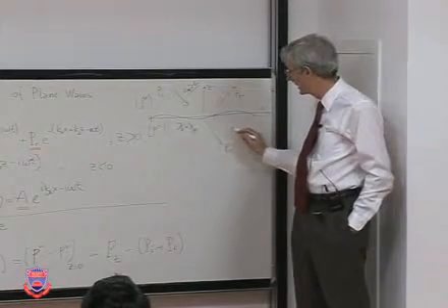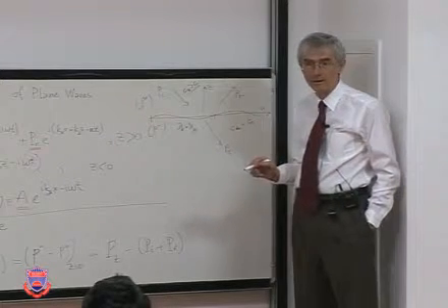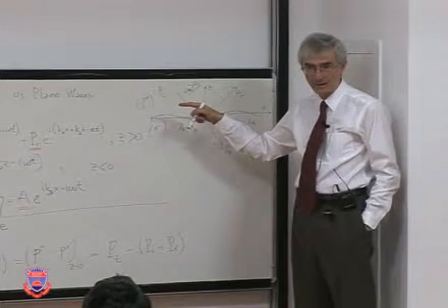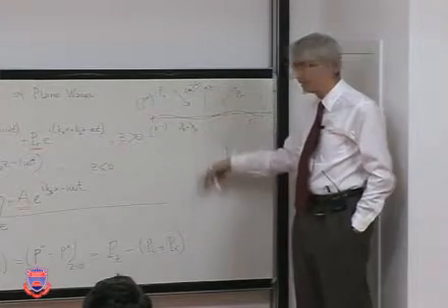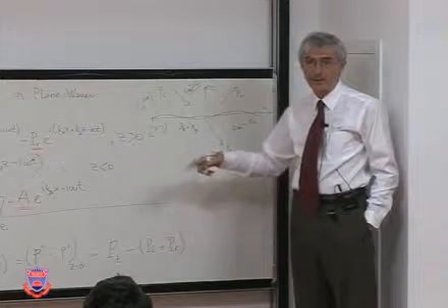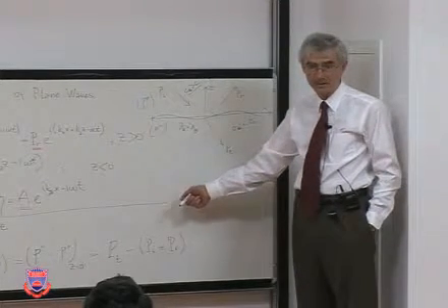But that may not be the case here, because sound is coming from the other side. So there may be a case where the excited sound may not radiate to the other one because its bending wave speed is smaller than the speed of sound here.